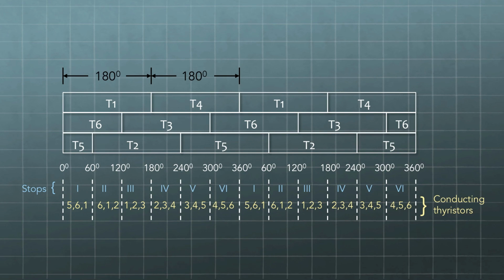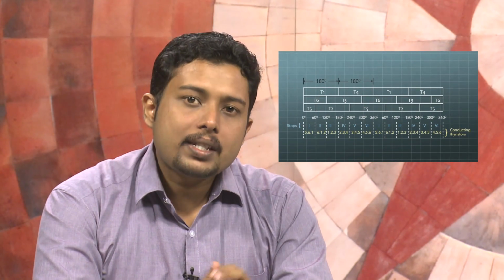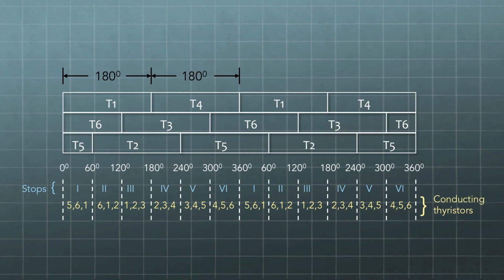Now let us have a look at the switching scheme involved to change the DC input to three-phase AC output. Here in the switching scheme you can see that the switching states of different switches are shown. It is to be kept in mind that no two switches of the same leg should be operated together.